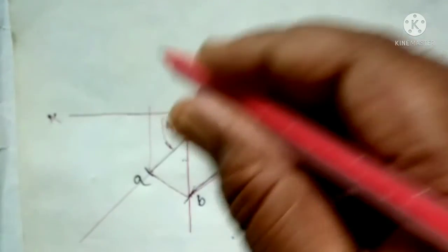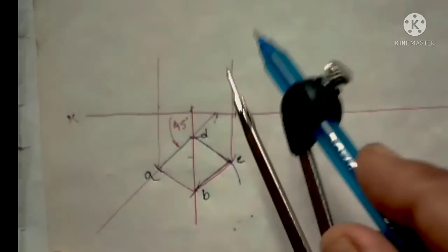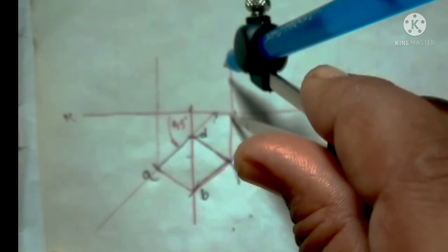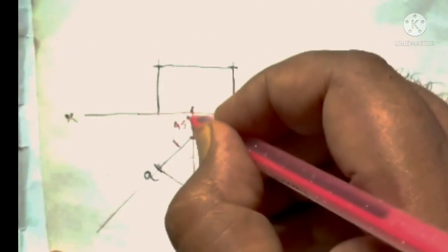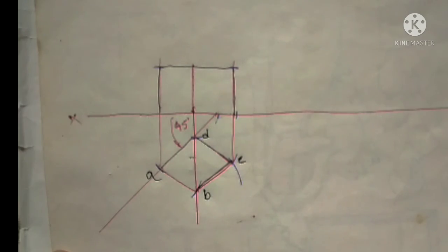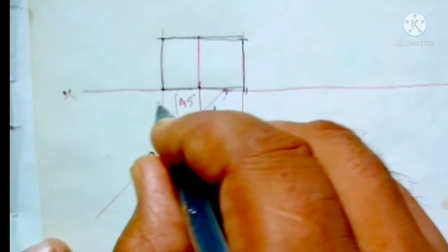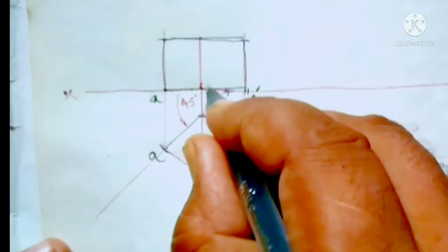Next, draw the projection line which is perpendicular to the XY line. Next, taking the same length, mark on the projection line the height of the cube. After that, join point to point by a line. We will draw this front edge on the projection line coming from point V. Then we will give the names such as A dash, B dash, C dash, D dash for the front view.